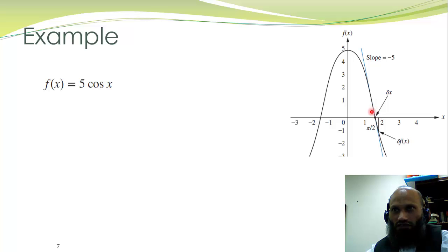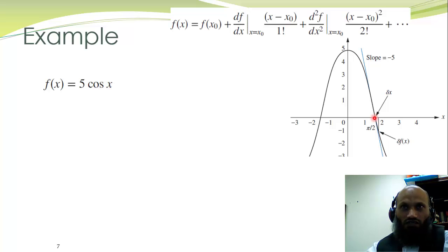We can see from this graph that this blue line, which is a linear approximation to this nonlinear curve, matches the original curve for points near the operating point. However, if we move away from the operating point, then there is a difference between this linear graph and this actual curve. So this linearization technique is valid near the operating point.